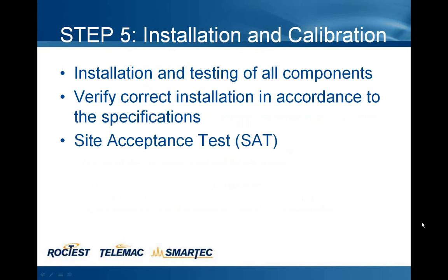Next step, installation and calibration. Obviously, we have to install, test, verify that the installation was carried out according to the specification. This usually terminates by a site acceptance test, where the owner verifies that the system has been installed correctly and everything is working according to the plans.